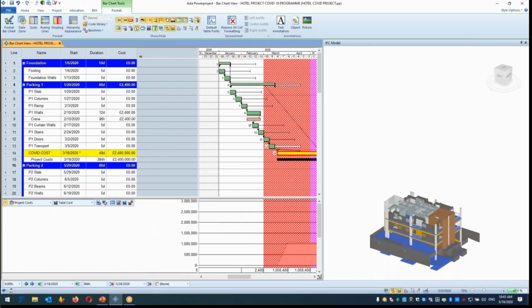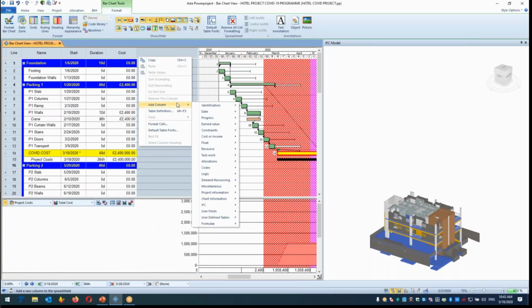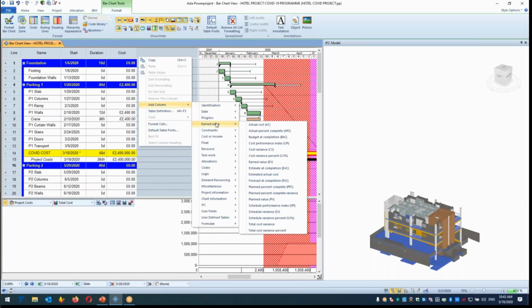But we also have possibilities for earned value management. If you go here to Powerproject options, there are earned value calculations. You can have cost variance, schedule performance index, and cost performance index calculation. And we provide, of course, the earned value S-curve. We additionally provide duration % complete out of the box, so without any resource assignment to tasks, based on the duration % complete you can get the project S-curve.